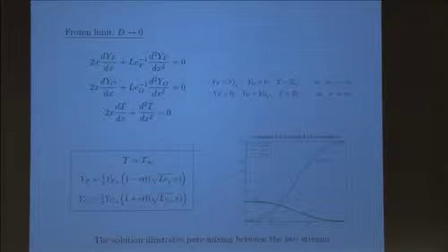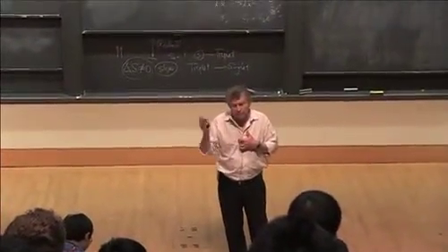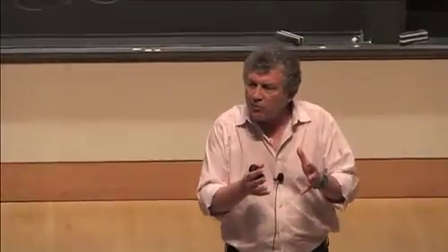Now, in principle, one can extend this analysis, and in fact this was done, by saying okay, now the Damköhler number is not identically 0, but it's small, and so let's study how the effect of a weak reaction occurs. What you should get in this description, which I'm not going to show in detail, is how slowly the flame ignites and there will be a weak flame that develops, okay? Which is not the Burke-Schumann limit. It's exactly the opposite limit.